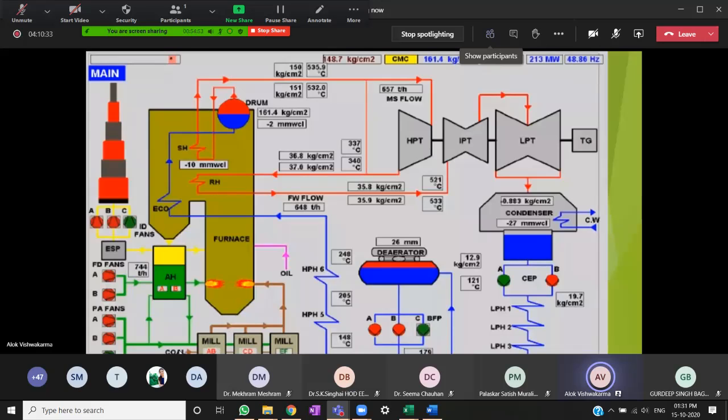After that, we need air also. So from crushing, there is the primary air fan. This takes coal from the mill and sends it to the furnace. So fine particles of coal are going to the furnace. This is the primary air fan functioning. This is coal. Here it is crushed. Then air is supplied by the FD fan. This is the forced draft fan. This is giving air because we need air as well as coal for ignition here.